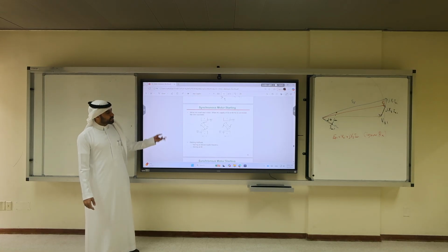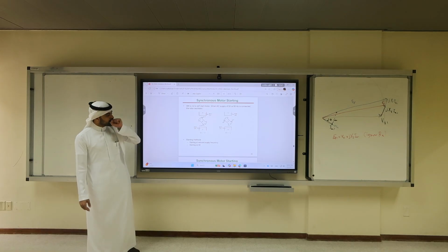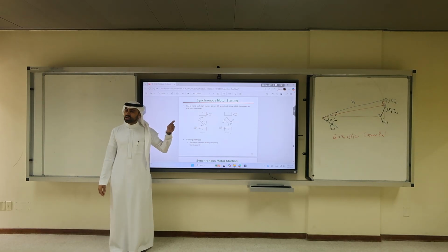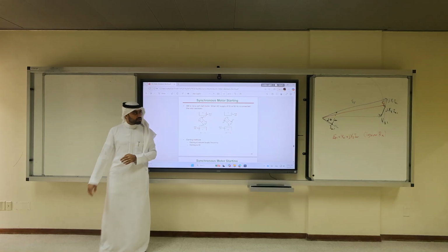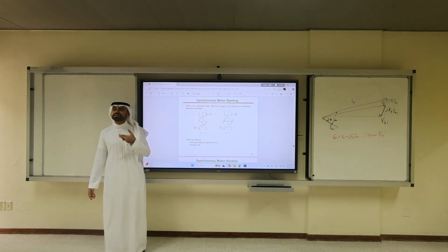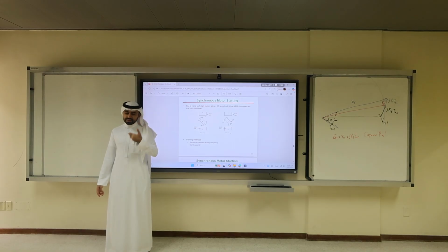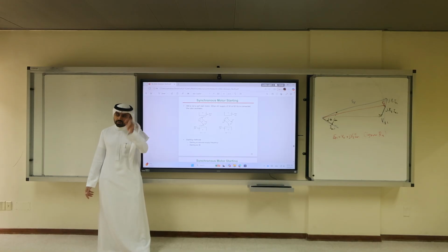That's okay. So enough talking about the synchronous generator. Let's talk a little bit more about the synchronous motor. Do you remember I told you in the synchronous generator the alignment between the poles is what determines the delta? One of the problems of synchronous motors is they are not inherently self-starting. They do not start by themselves. You have to either synchronize them manually at the same speed or use some techniques.